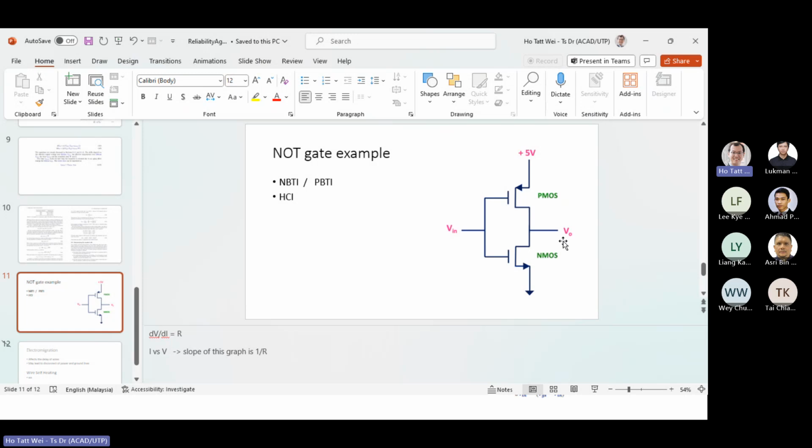So the whole idea is for you to understand that from this Liberty file, you can estimate R, you can estimate the capacitance at the gate here, you can estimate the capacitance at the gate here. So if you're given that model, straight away you can extract the R and C parameters from your basic transistors, your standard cells, without looking at the data sheet. You can do that from a circuit parameter, and then you can start estimating the RC delay.